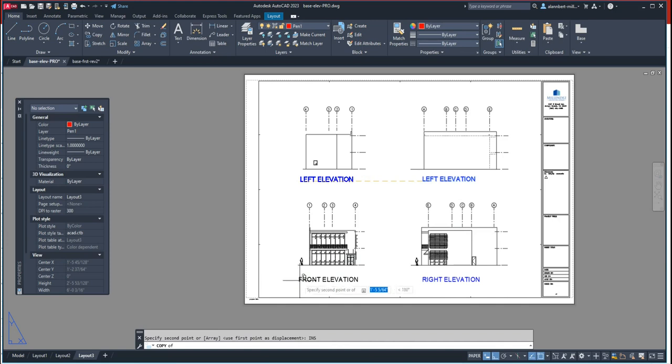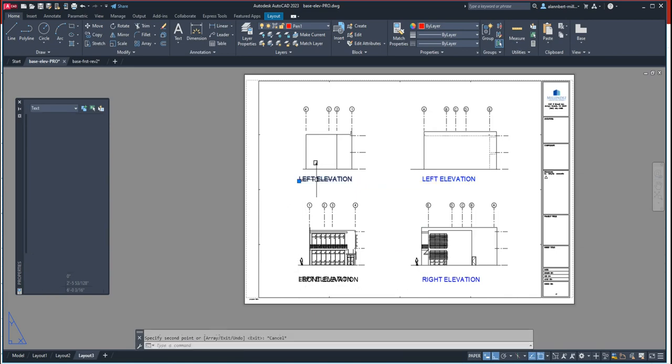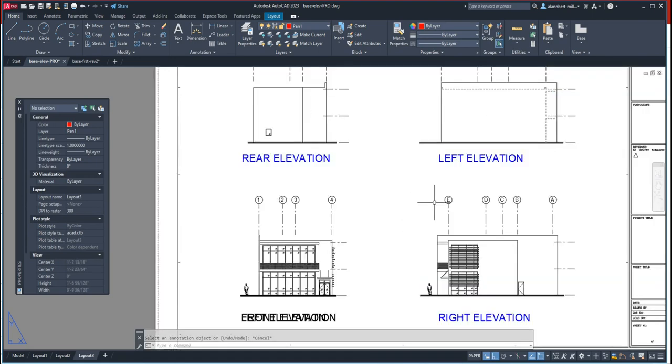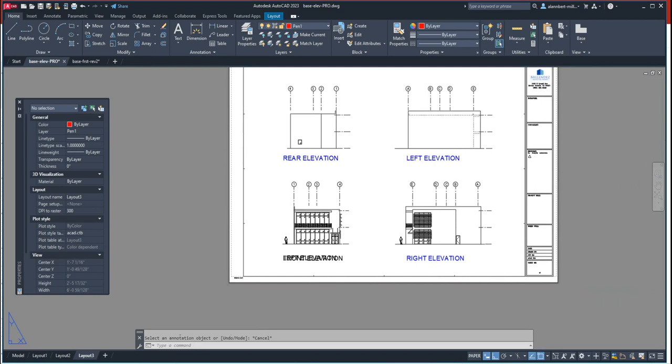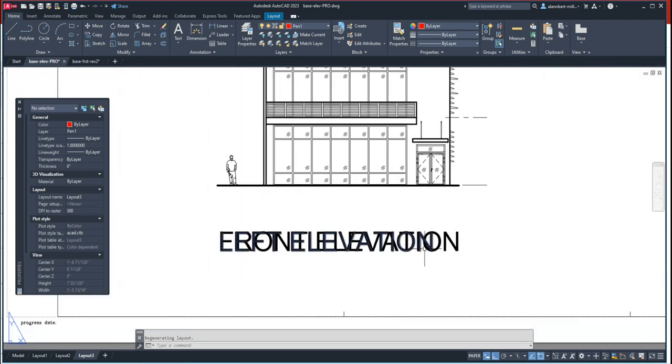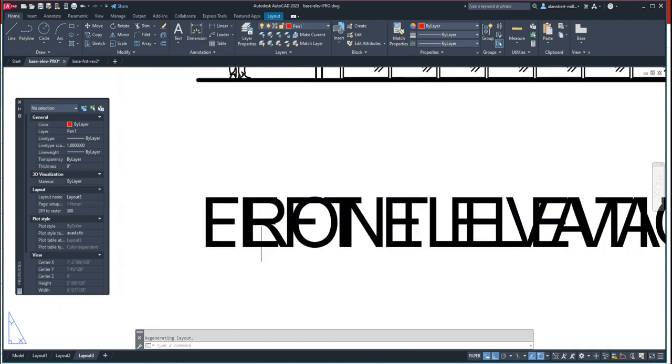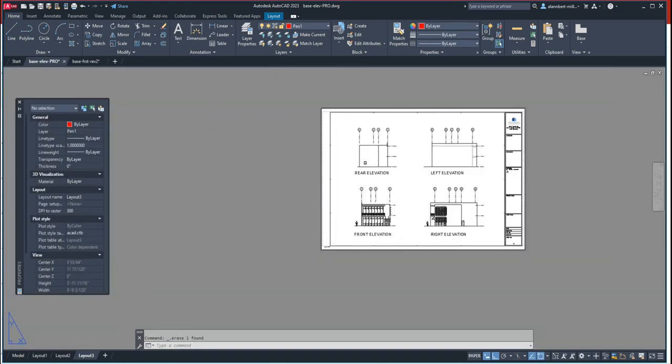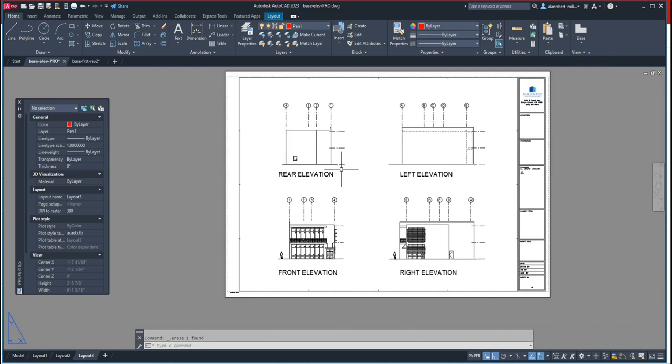So you simply point but not click, and then AutoCAD should remember it. Oh, no. So let's just align that manually. There you go. And then call this rear elevation. They're blue because they're pen 5, but if I regen again, they switch back to black. It's like I made a copy here. Which one is my copy? There you go. All right, so that's just the names of these drawings.